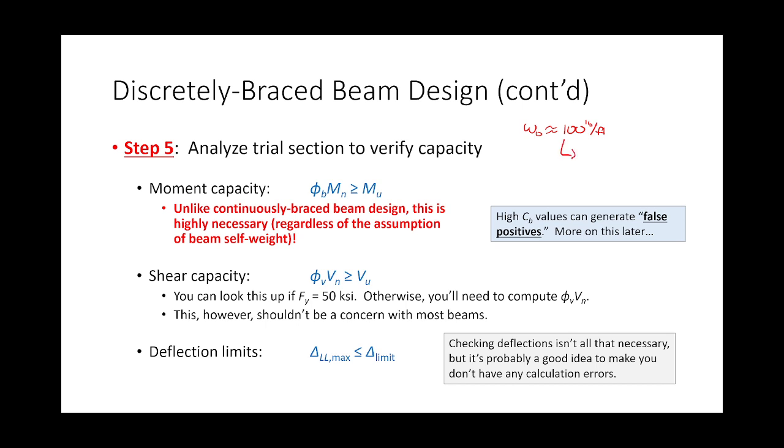And let's say I do a bunch of math, do a bunch of structural analysis, go into table 310, and I get a W24 by 76. Do I need to go back and update my moments? No. Why? It's already exceeded that. If our assumption is heavier than the beam's actual weight, then we don't need to update that assumption.